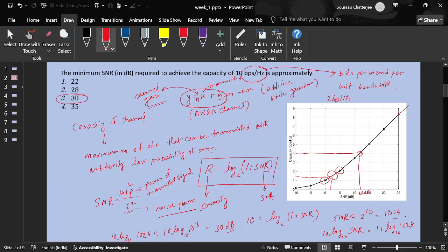So as per our discussion now, let's say I'm operating at this particular SNR. Sorry about this drawing part. So let's say it is somewhere around 2.5 dB. So at 2.5 dB I find the corresponding channel capacity as 1.5 bps per hertz. So I want to design my system in a way that it achieves the capacity.